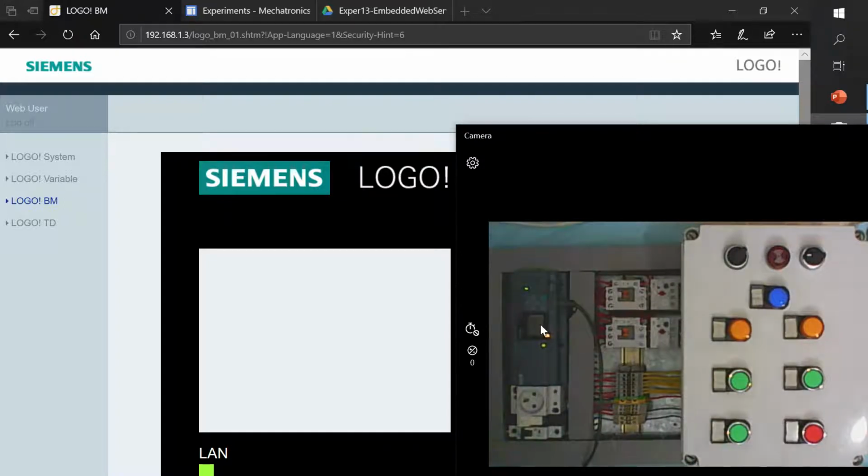So let's run it another time, and now we start the system, and the message displayed on the PLC right now is M1 running. So this is motor 1 actually running, and we can display another message that is M2 is running. Whenever we now test the overload condition, remember that in the relay logic circuit we are unable to tell explicitly that motor 1 or 2 actually is the cause of the overload.